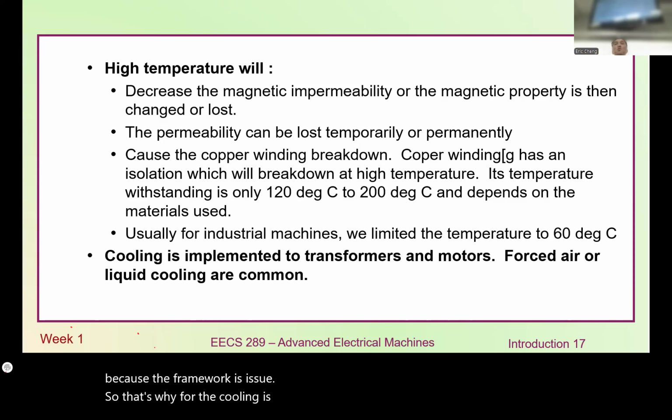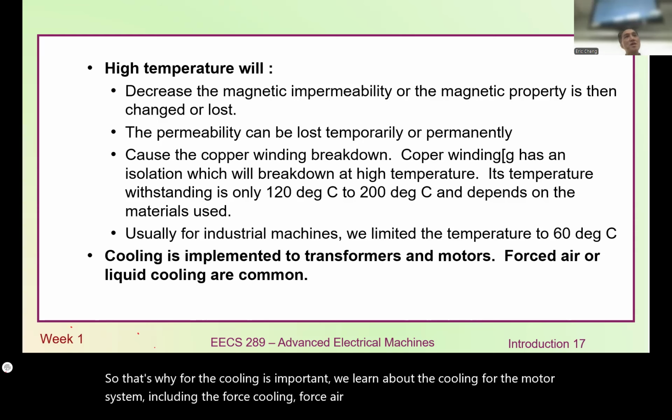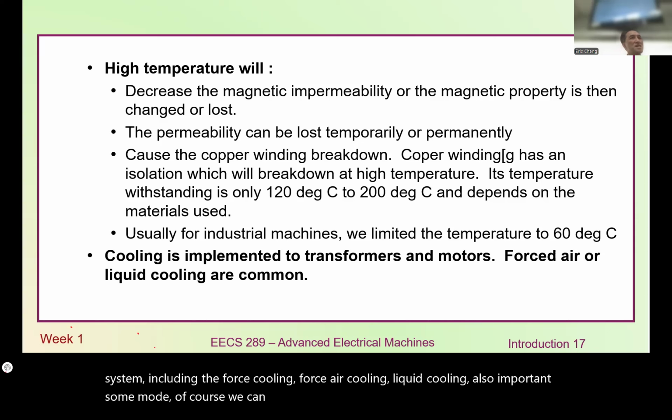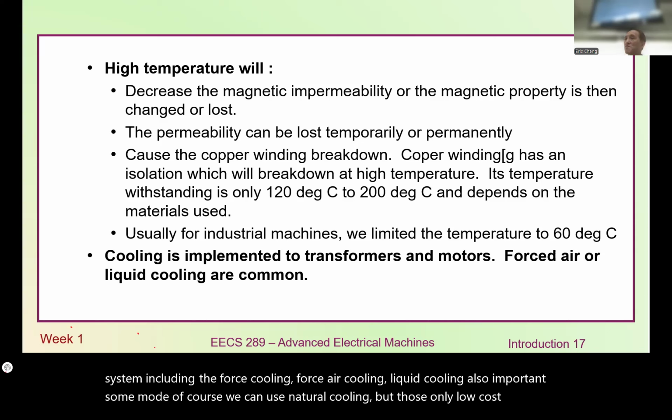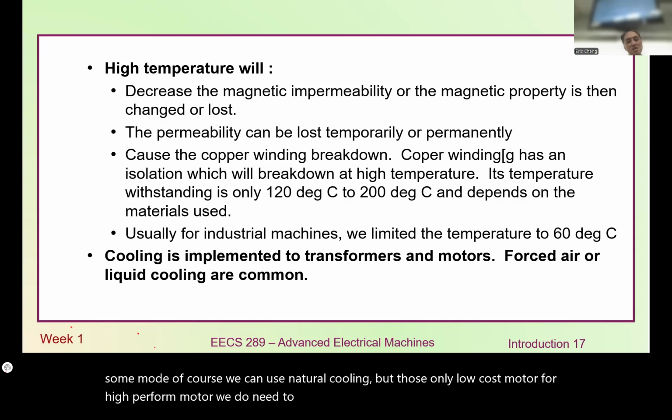So that's why cooling is important. We learned about cooling for the motor system, including forced air cooling and liquid cooling, which is also important. Some motors can use natural cooling, but those are only low-cost motors. For high-performance motors, we do need really strict requirements for liquid cooling or forced cooling.